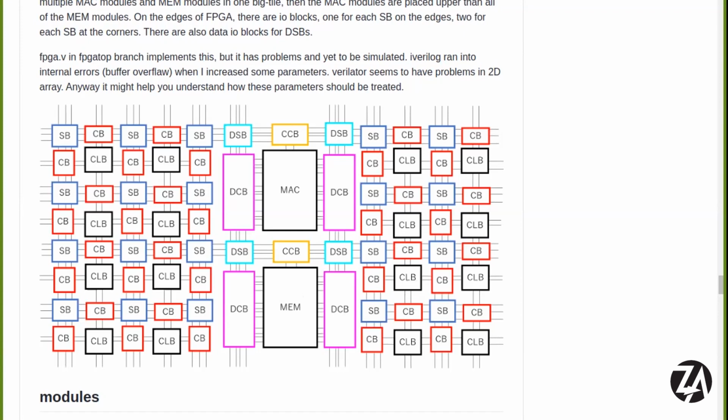So a question about the target to ASIC flow then. Did you harden each of these little blocks and then place them? We tried everything, because initially the tools had a lot of problems synthesizing dense tiles that had a lot of cells in them, and they're very large.